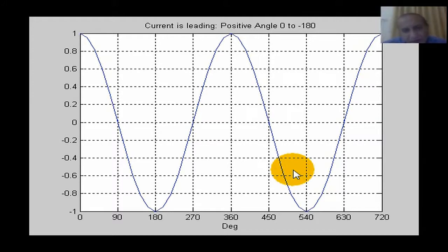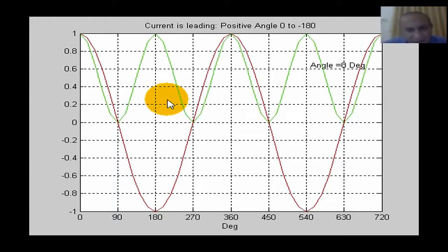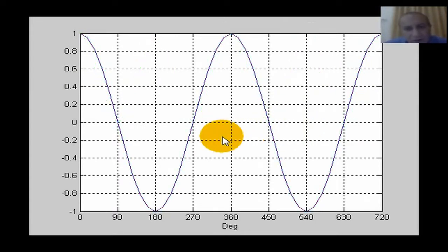So this is our voltage source. We start with 0 again. To remind you, we have a positive power at double the frequency. Every time we have double the frequency, but with a shift in the power. So this is the case for a 0-degree phase shift. We have positive power all the time, average positive power, with no negative power. It's totally consuming the energy in the load.